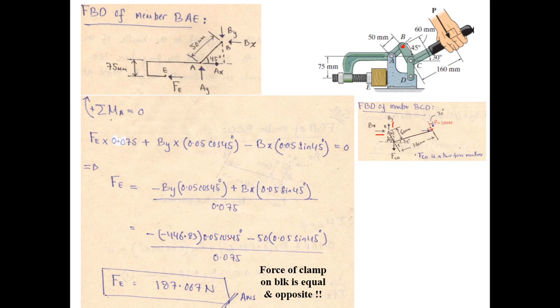So this is how we solve the problems on machines. The only thing to remember, which is very vital and important, is that whenever you are dismantling members connected by a common support, you have to show the reactions in opposite directions, so that when you again combine or join the members, the reactions internally cancel out.